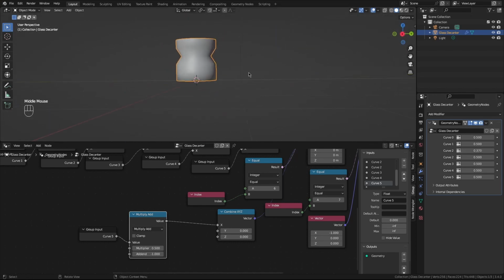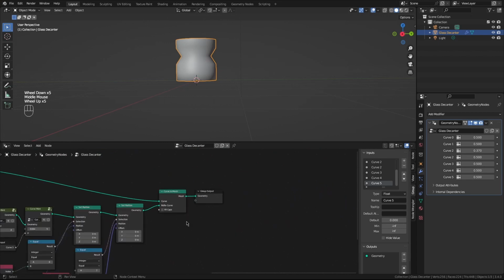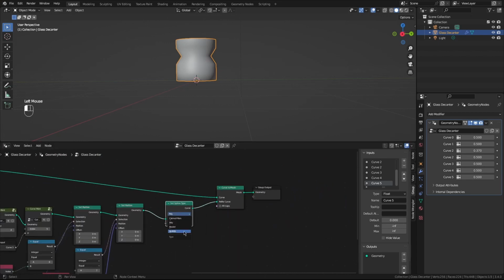And we have the ability to control a curve. Now, right now, it looks a little bit pointy because it's a poly curve. That's more like it. Could use a Bezier, but then we'd have to deal with the control points, which would be a whole lot more complexity. Admittedly, more flexibility, but NURBS is just a nice compromise for both of those. Before we go on, I'd like to give this some more decanter-like shape. So let's give it a bit of a neck with a flare out. I think that'll do it. Which is something a little nicer to look at.